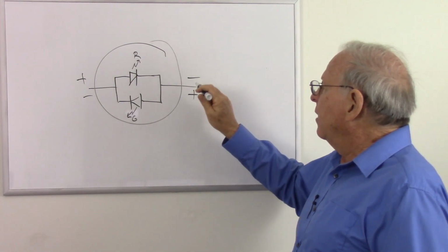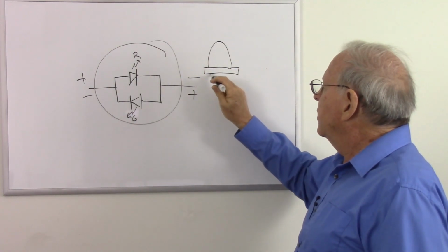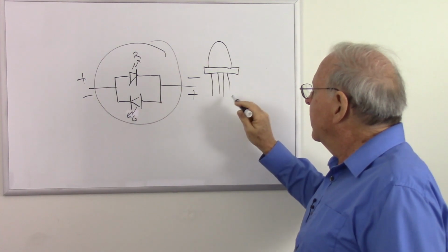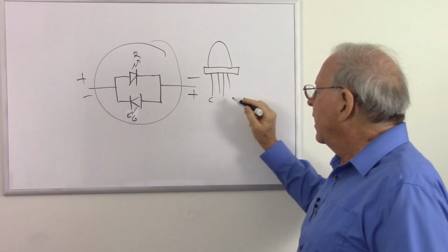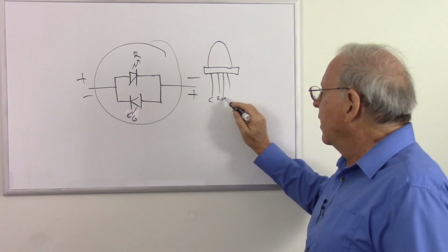There are other multicolor diodes that work a little differently. The package looks something like this. Instead of 2 wires, we get maybe 3 or sometimes 4. And there's a common connection, a common cathode, and then the 3 anodes, we can get red light, green light, or